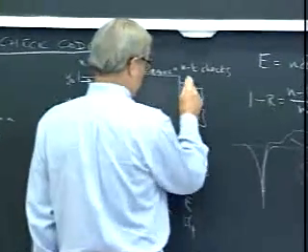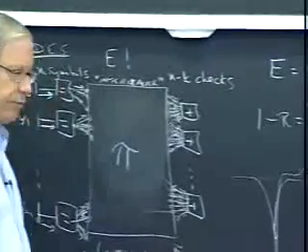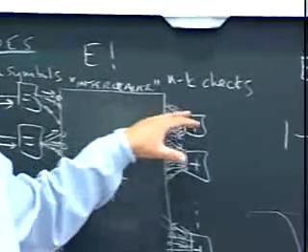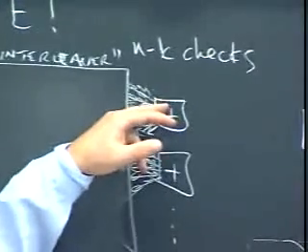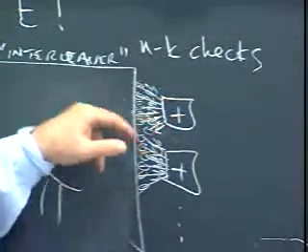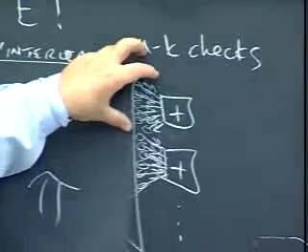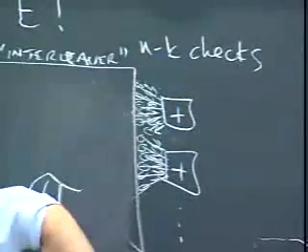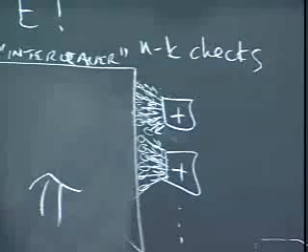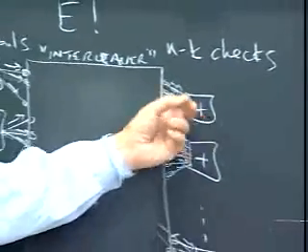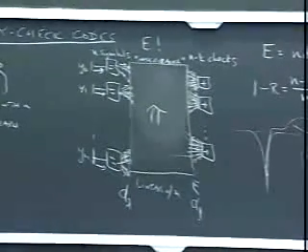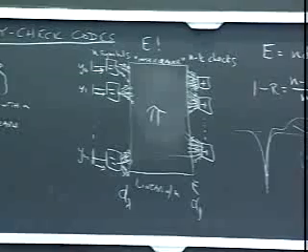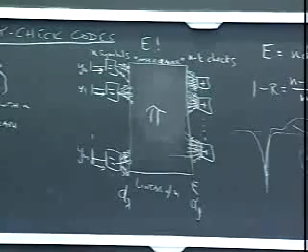Each one of these is based on the D minus 1 other inputs. All right, so it ignores the message that's coming in on that particular edge. It uses all the other messages to give an extrinsic message going out, which you could combine back here or here, the same thing, to give you your best overall APP right now from your right-going and your left-going messages.